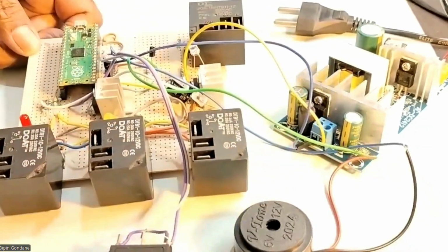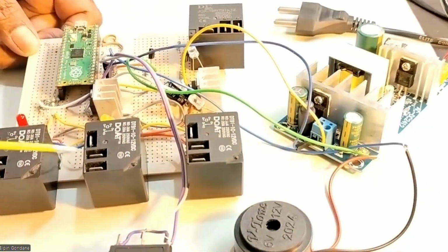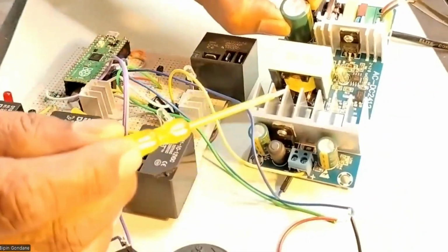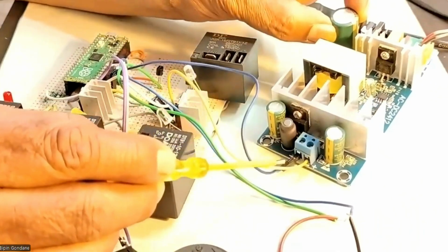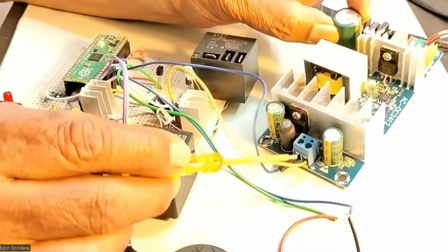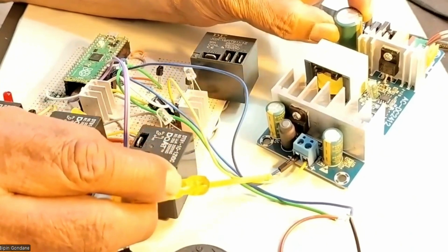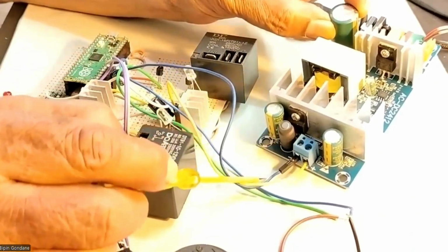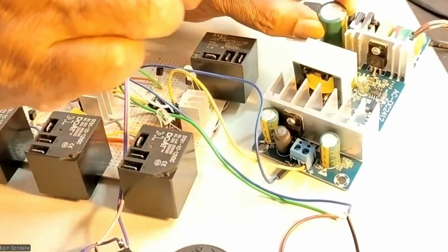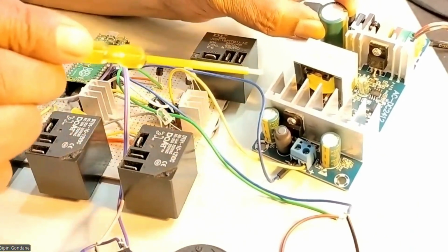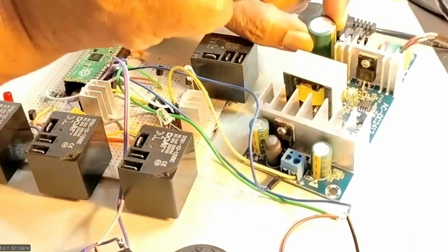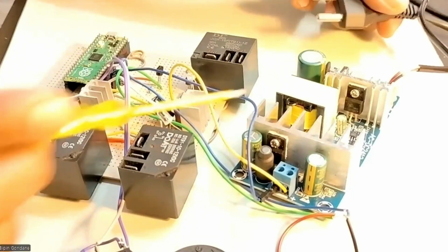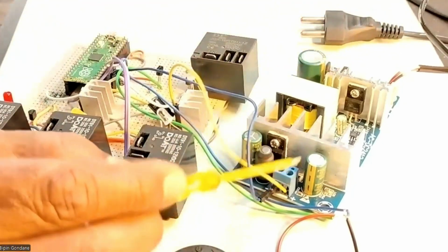For the whole thing, the 5 volt, 12 volt, and the relays, the main power supply is here. So this is my main power supply. I will just try to show it to you. It is a 24 volt output, 10 amps power supply, or 100 watts. So you get 24 volts DC output. This complete circuit is an SMPS, and wattage is approximately 100 watts. It has an AC input, so I can connect the AC also, and through this the DC is made.